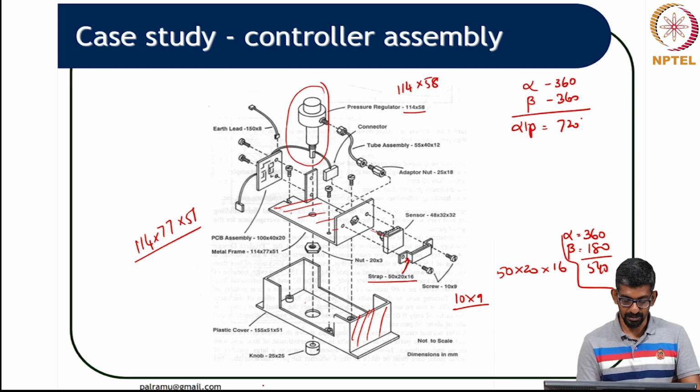So, what they are telling is you can kind of integrate this guy into this guy, so that you can get rid of this, you can kind of get rid of this and you can get rid of this. So, 3 screws you can get rid of, but you need to integrate this guy into this guy. He is a metal frame made out of some material, and this is a plastic cover that is made out of some material. Okay, but you have to try to integrate this. It might mean that you will have to change this material. Okay.